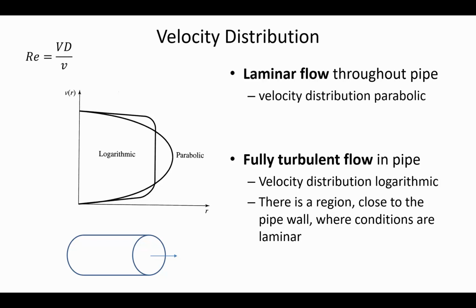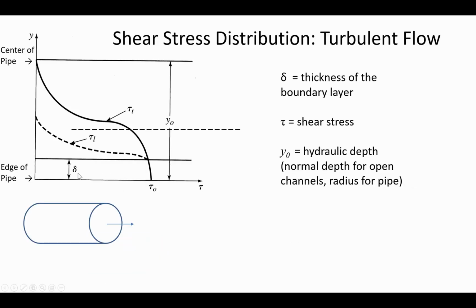You know, average velocity is flow rate divided by cross-sectional area. You did that in the lab plenty of times last semester. Q divided by A equals V. Well, the V that we use in that formula is the average velocity, but there are lots of different velocities. And so we're talking about the velocity close to the pipe wall, which is a low value, and it causes this laminar sublayer.